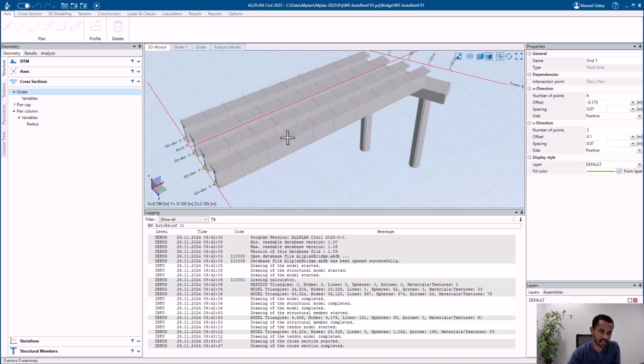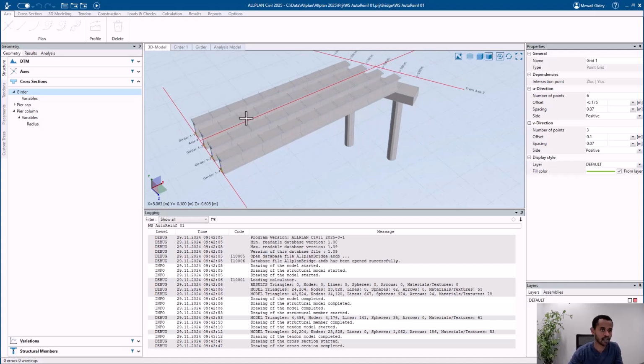So based on the lengths, based on how far it is, maybe apply the spacing to be different. So from both ends, like 2 meters in, have a different spacing. For example, for transversal bars, you could set that up as well. So different things that you could do. Moving on to our second example, which is the retaining wall.